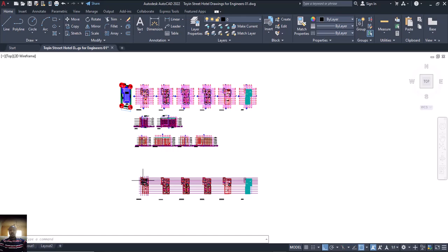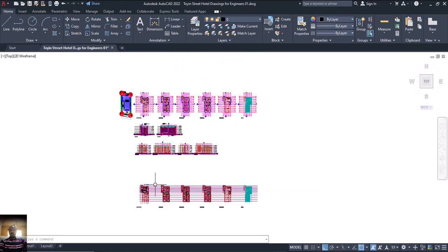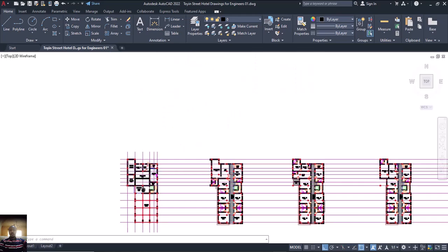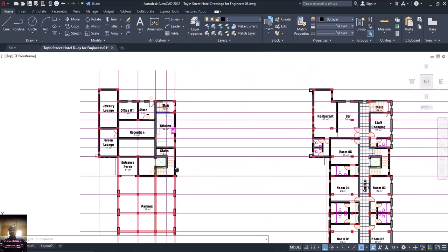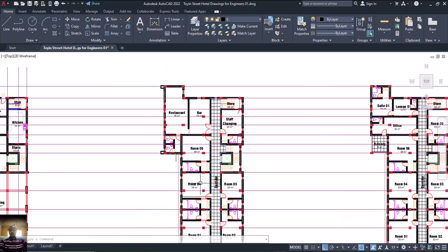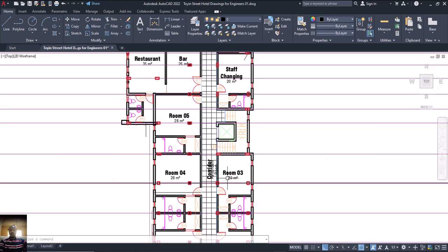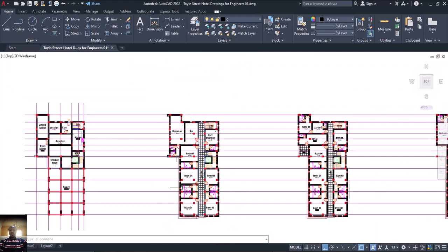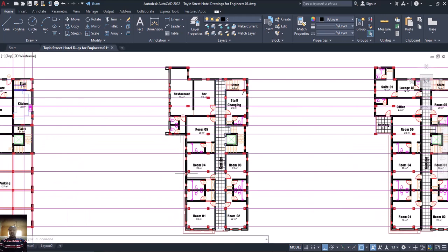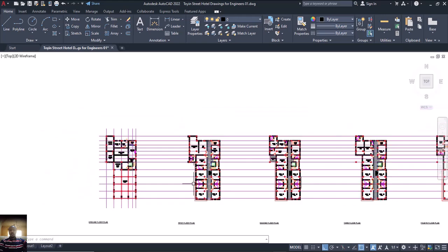Last time we did the introduction on this particular drawing, and we also did part 1, whereby we did the GA for this. When we superimpose this GA into this, and we have done a lot of explanation on this, you can now see that some columns are not in line with the wall, which means we are going to make some adjustments, some shifting. Which means that the structure is not typical.